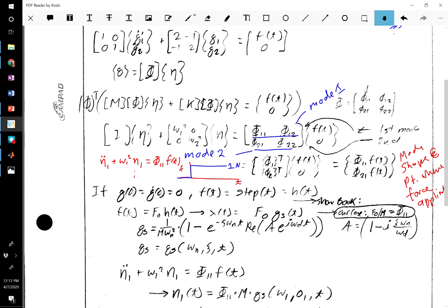And if we go to the book, to Appendix B, we can eventually find that force in the appendix, and with a little bit of manipulation, we can rewrite it in this simpler form right here. The expression given in the back of the book is a little more complicated, but basically we have 1 due to the forcing, 1 over m omega squared. That gives us a k term. So that says that we get a static response of f over k.